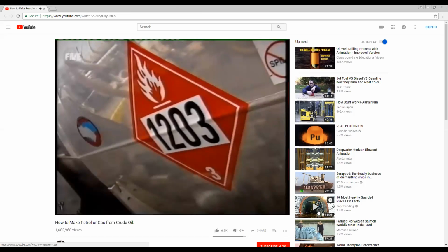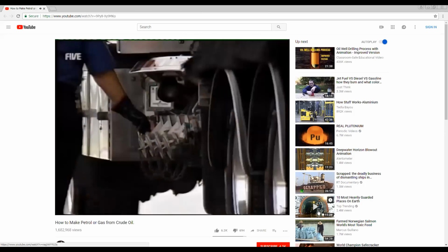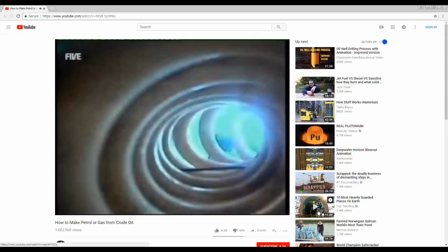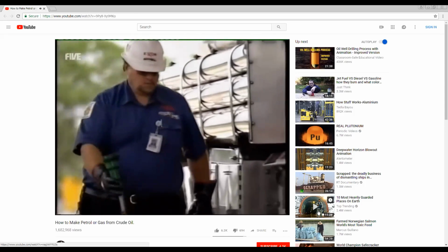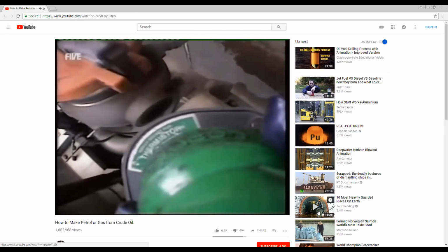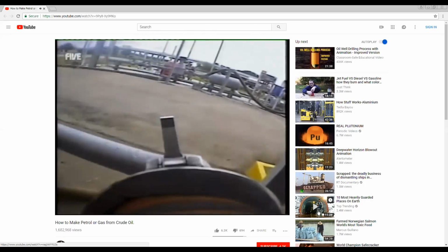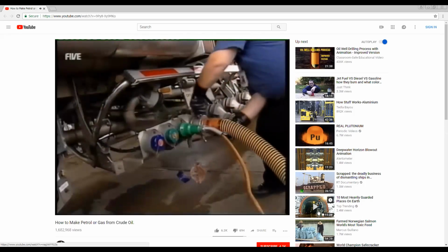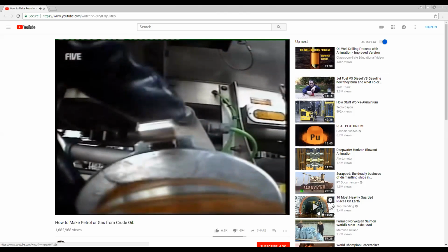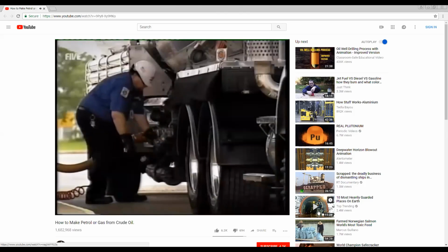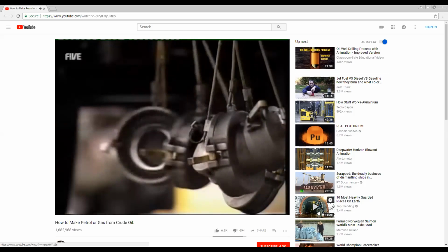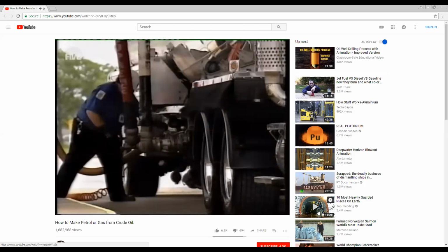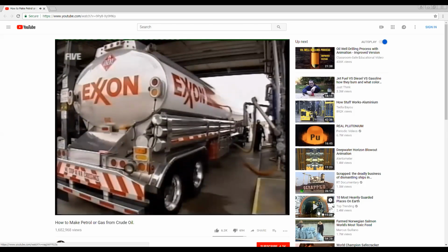The metal bodywork can generate sparks from static electricity. So first a cord is attached to ground the trailer and also activate the overflow protection probes at the top of each compartment. To cope with the threat of highly flammable vapors escaping, a second pipe, known as the vapor recovery pipe, siphons off any leaks, which might otherwise escape into the atmosphere. Only once these are in place can Bradley connect the fuel lines and begin to pump.